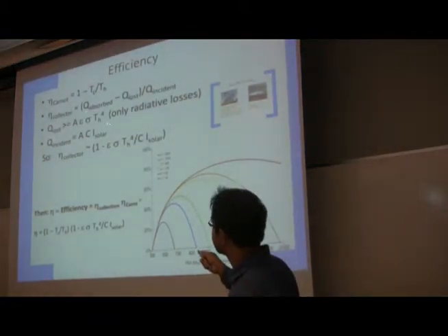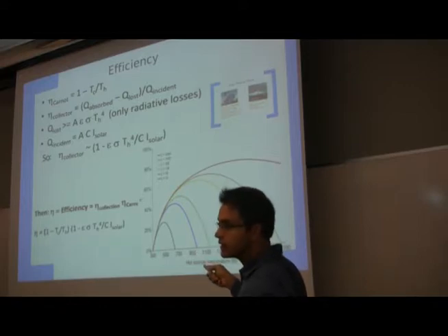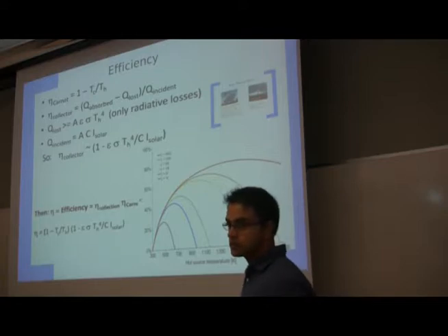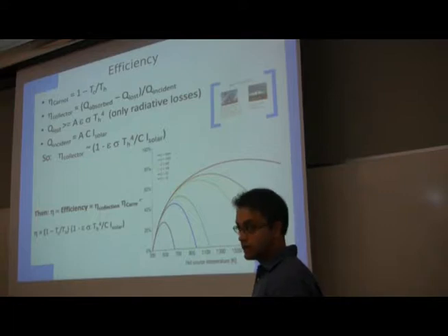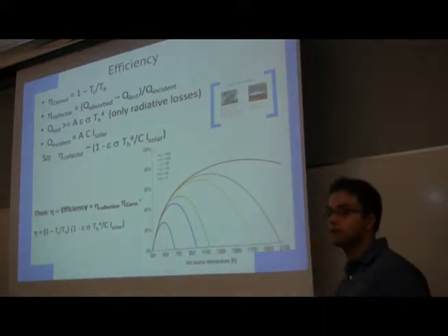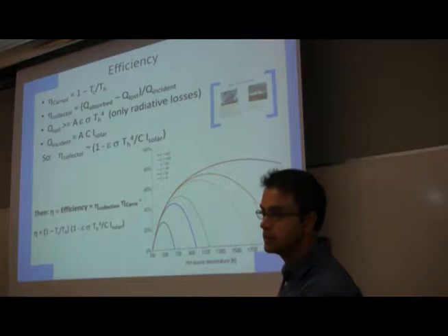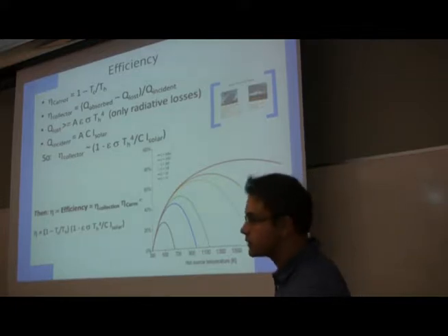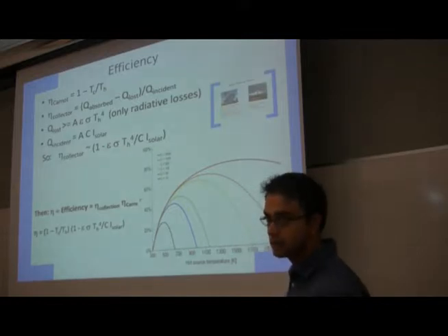That's the hot reservoir. That's the heat loss, right? Now, epsilon is essentially what's called an emissivity, which is a measure of how different from an ideal black body the actual reservoir is. I'm not going to go into much detail, but if epsilon is 1, it means it's an ideal black body. If it's less, and it's always less than 1, it means it's a slightly poorer absorber as well as an emitter than an ideal black body. That's all that means. It's a constant called an emissivity.